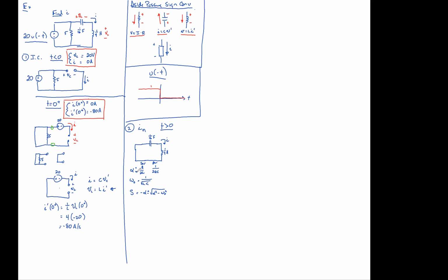Remember, as another small aside: if it's in series, the currents are equal, and if it's in parallel, the voltages are equal. And for this one, it's both. So you can use either equation, whichever one gives you a good result.